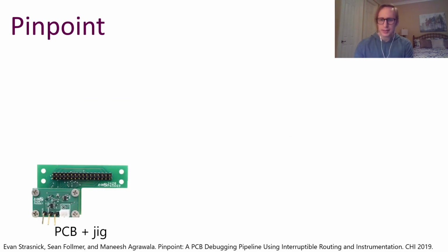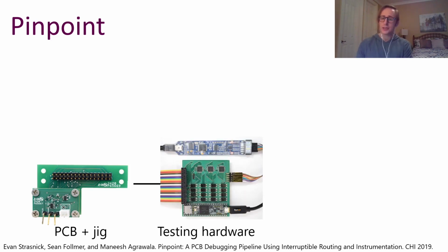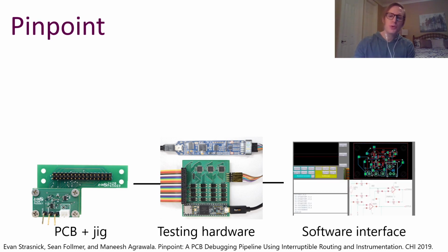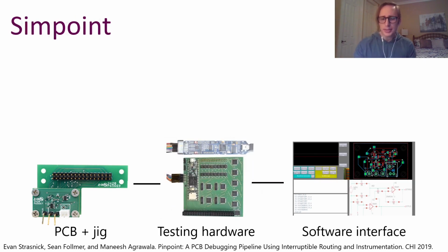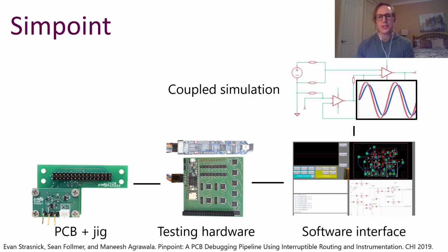Pinpoint generates for the designer a custom jig board that interfaces their PCB to testing hardware, allowing the user to perform their debugging operations in a software interface as opposed to manipulating the hardware. Pinpoint uses new testing hardware capable of modifying physical components within the circuit and routing external components in their place. Pinpoint software then also manages the simulation of the user's circuit, represented as a SPICE netlist.